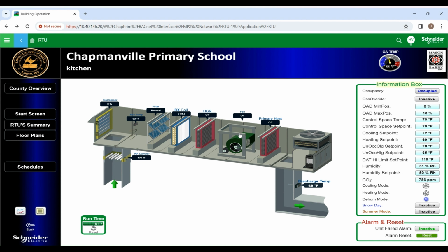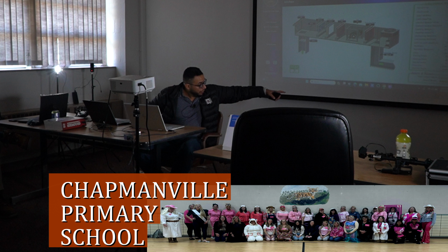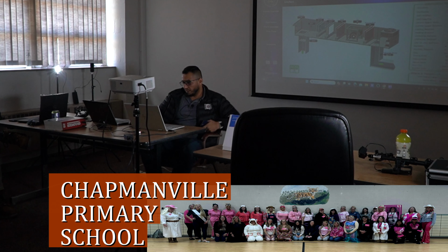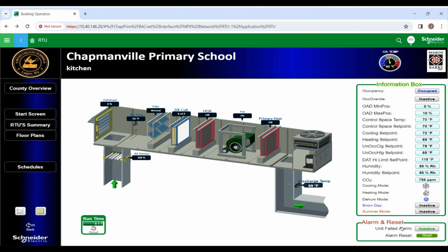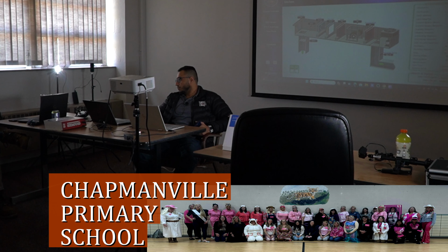It's a trigger for every other feature in it. On this side, you have alarm and reset. That's what we call a unit failed alarm. Basically, when you lose a fan status, fan not running anymore, that is the ultimate failure because you cannot do anything with it anymore.